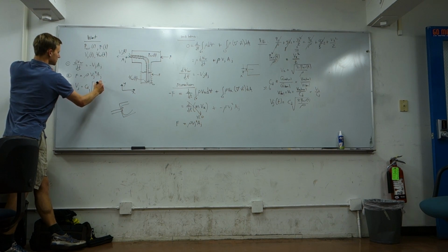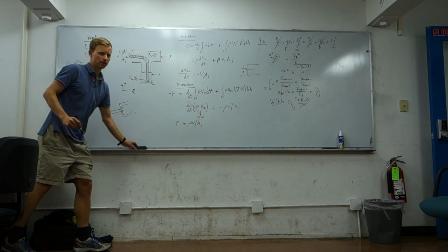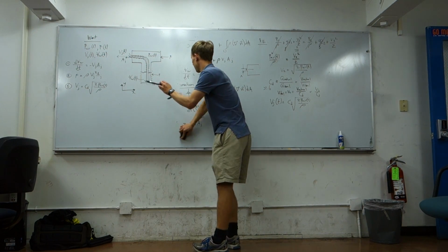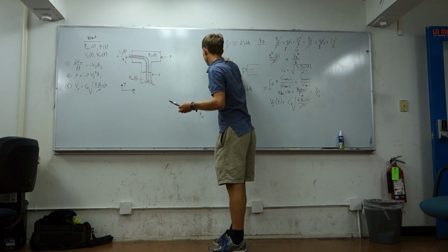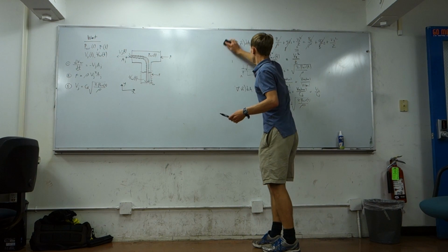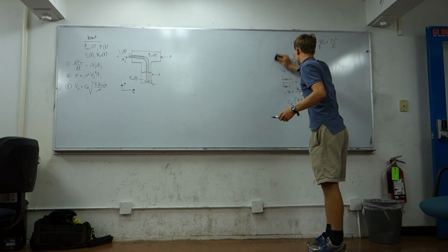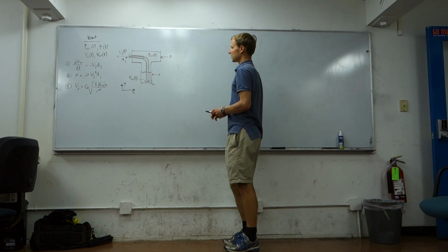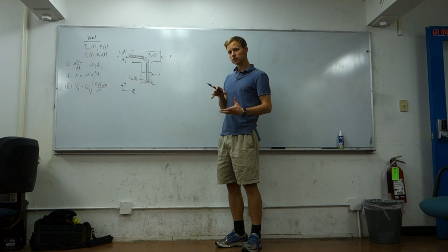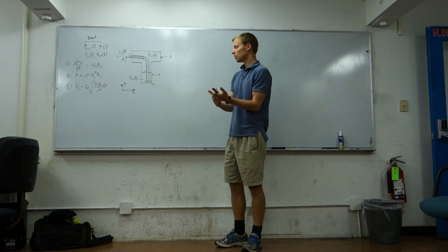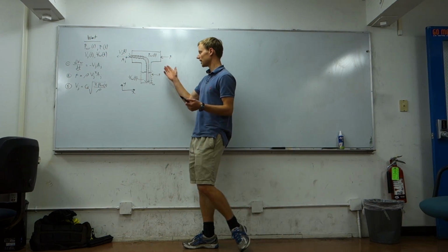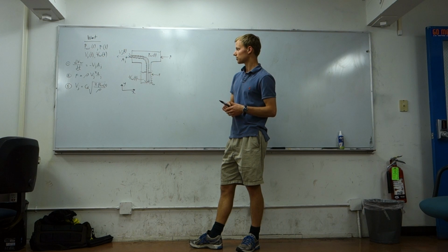So we definitely need one more equation still. And this last equation is always the one that people tend to forget. So right now our only unknown we haven't accounted for is P air. So we need to use our E30 knowledge to come up with an expression for how P air relates to the other variables. Whenever we have a process that involves air expanding, we need to think of a variable which is going to remain constant during this process. So definitely not pressure. No reason for temperature to remain constant because there's no heat flux. I'm not allowing for any heat flux. We're not providing any heat flux to counteract the temperature drop due to the expansion.